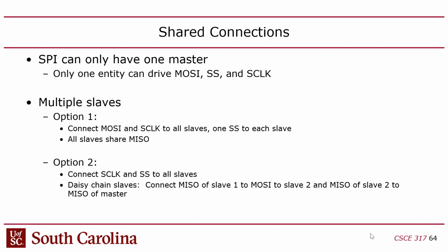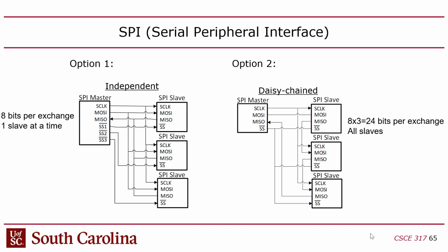Okay, so if you want to have one CPU and multiple peripherals on an SPI, you can do that. The problem is that you're limited to those four wires, right? And the four wires are actually named assuming there's two sides. So one way to do it is to have the master have one slave select for each slave, and the slaves just have the 4-wire connection.